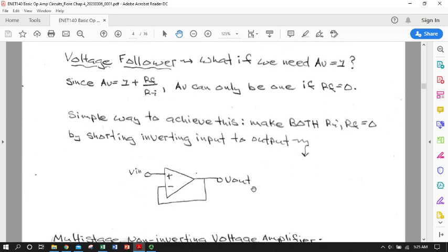So this schematic shows us our absolute simplest voltage follower, where we've effectively got infinity for R sub I. We've got an open. We haven't connected the op amp to ground at all, so it's floating unless we have a ground on the input, which may or may not be advisable. But we definitely have an RF of 0. So you can see we have no feedback resistor, we just have a 0 resistance wire. So this defines a classic voltage follower.